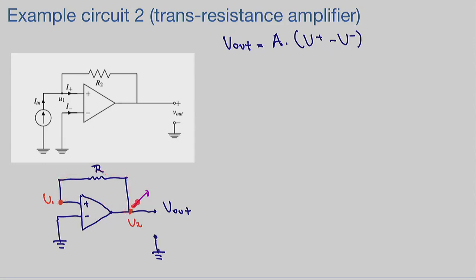What's the voltage definition here for a resistor? So VR is going to be what? U2 minus U1, right? So if I tell you now to check for negative feedback, I'm making U2 bigger, what's happening to U1? Increasing, yeah. So U1 increases.